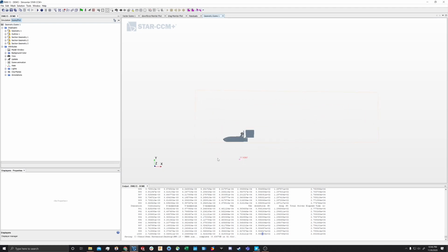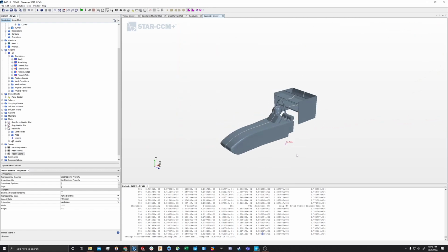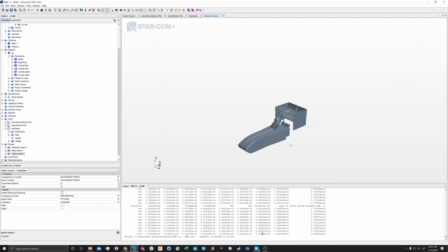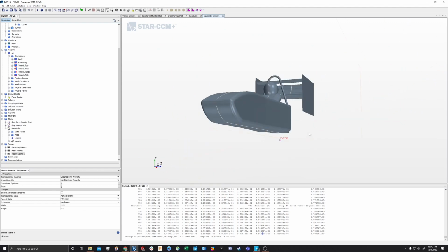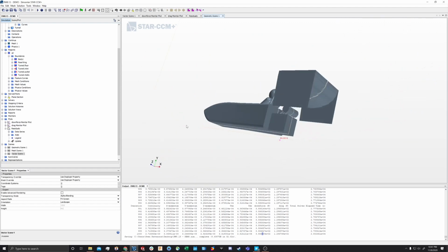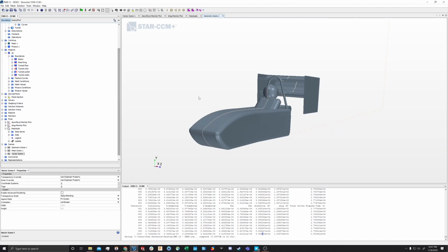Okay, the final analysis tool I'm going to go over here is how to create streamlines. These are pretty valuable. They show 3D flow. That can be useful in a lot of ways, especially for analyzing 3D bodies here. The planes show 2D stuff, which can be useful. They're pretty simple, but when it comes to these three-dimensional bodies, we definitely want to take a look at how that flow is working in 3D.